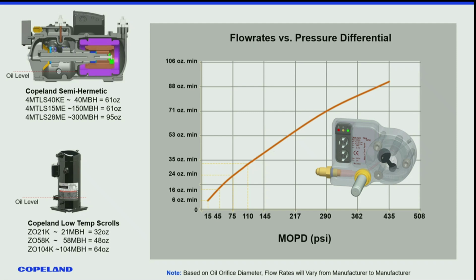On Bitzer's stuff, they actually show a regulator like that. So it has been done. I have to check. Seems like a real critical thing, to maintain that exact pressure you want. It can be, but it forces you to tune the flash tank and the suction so those two don't get out of whack, so you maintain that differential. Yep, that's a good point.